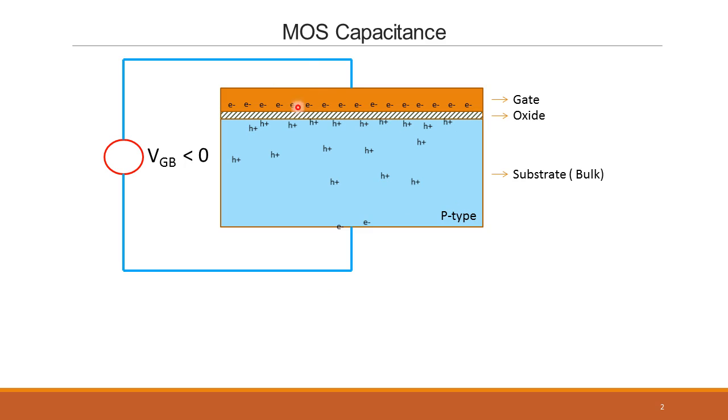So now we can see that there are excess electrons here and excess holes here, and this looks exactly like a parallel plate capacitor. Okay. These are all mobile charges here, and these are also mobile charges, separated by an oxide, which is, let's say, T-ox thick. Then you get a capacitance across these two points. Okay. You get a field from the positive side to the negative side, which means there's a voltage drop. And this, as I said before, is exactly like a capacitance. Two terminals of a capacitance, the poly here and the substrate with the excess holes here.